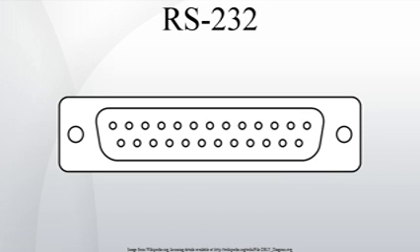Secondary channel. There is a secondary data channel, identical in capability to the first. 5 signals, plus the common ground of the primary channel, comprise a secondary channel: secondary transmitted data, STD, secondary received data, SRD, secondary request to send, SRTS, secondary clear to send, SCTS, and secondary carrier detect, SDCD.